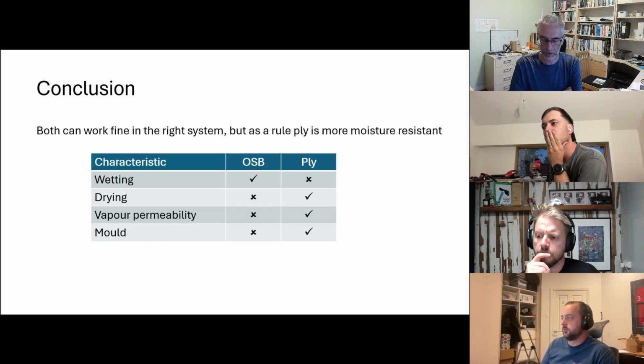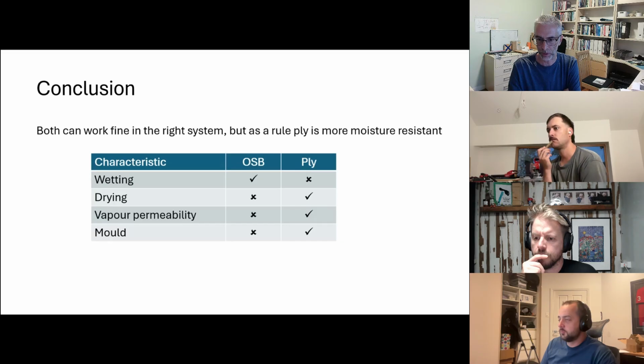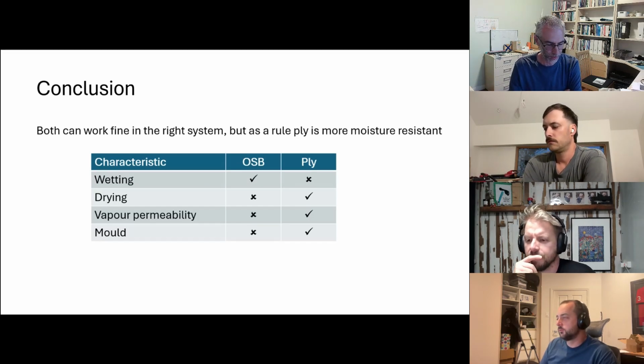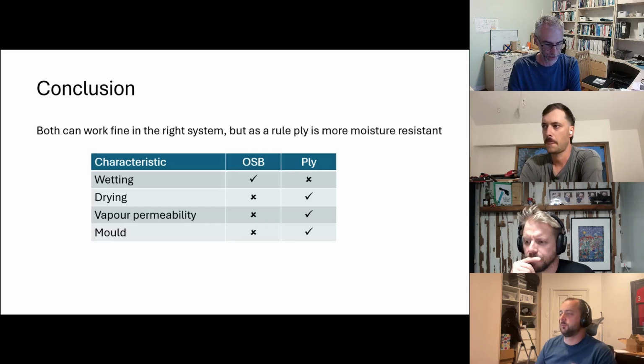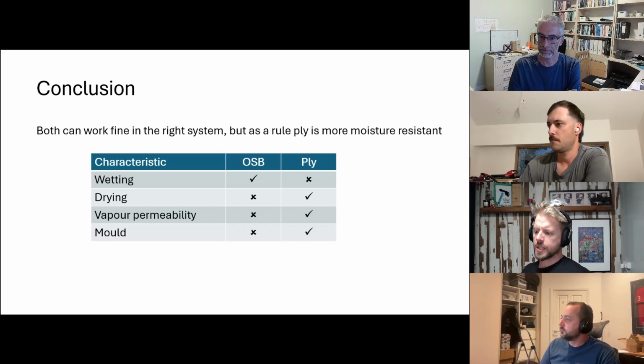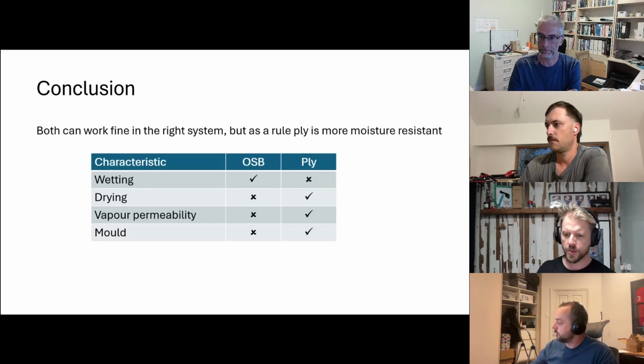So, Hamish made this point, I think, before we started, that the one advantage of OSB is that you're using your otherwise waste material from the tree, the less useful bits of it. But that will also disproportionately be all sapwood, the really young wood that's got higher sugar content and therefore is more mold available. So I don't have evidence for this, but I'm hypothesizing that perhaps that would make the particular age and species of timbers used in OSB more readily available to mold than the ply.